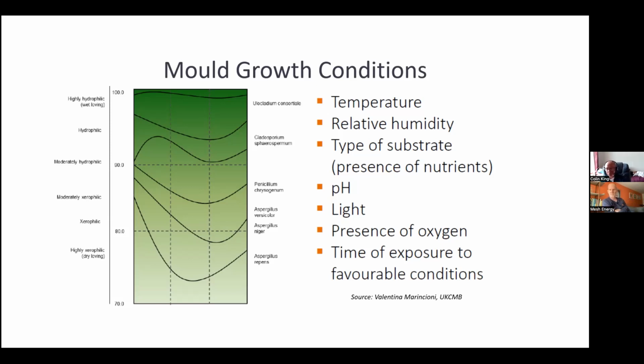he's saying, regarding old buildings, can you elaborate on the contribution to raised levels of damp and condensation due to, for example, the wrong paint, wrong mortar, wrong plaster, use of cement, inject DPCs? Absolutely. When you look at buildings that were constructed probably prior to, I don't know, 1920 is an arbitrary date, they didn't have DPCs. They don't need a DPC. They've never needed a DPC.